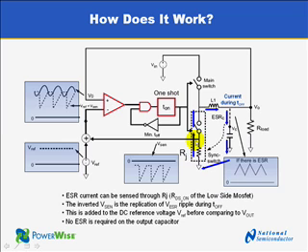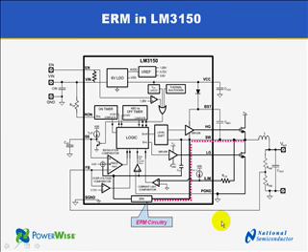So basically, we remove the undesired ripple from the output and reconstruct it at a place where it does not hurt us, the RDS(on) of the MOSFET. This means emulation of the output ripple, or so-called emulated ripple mode.